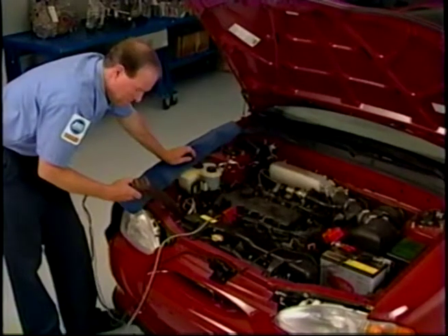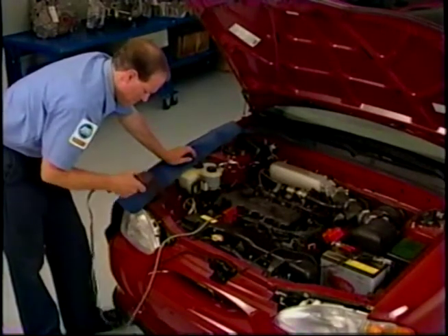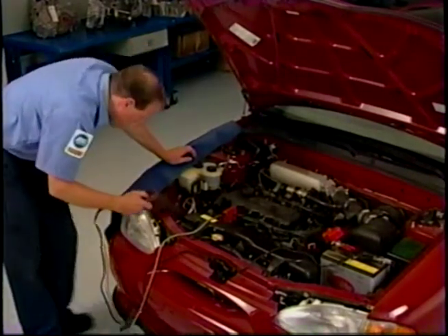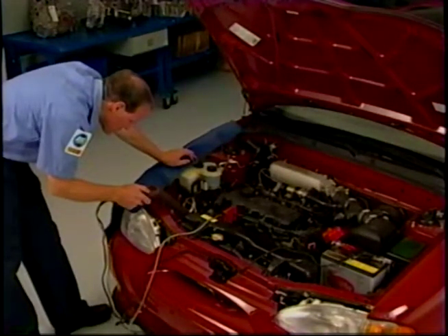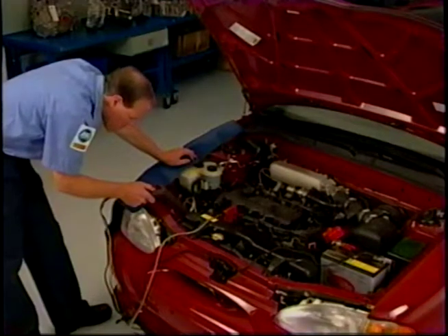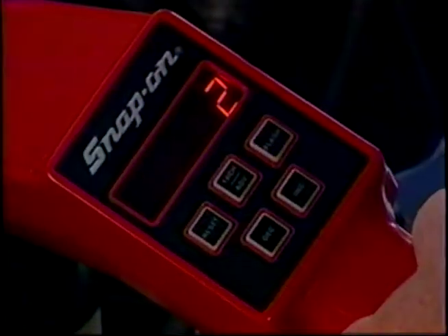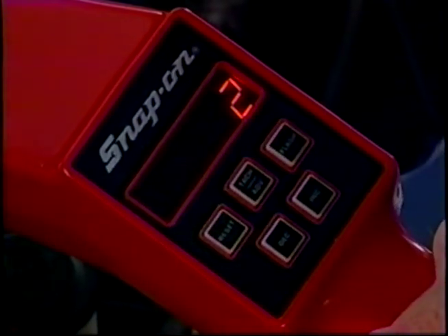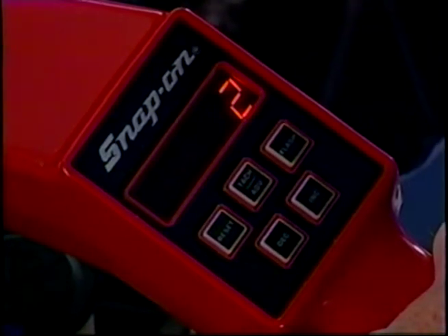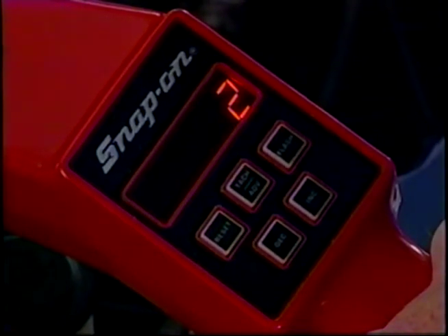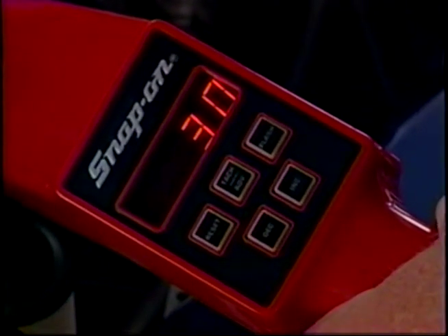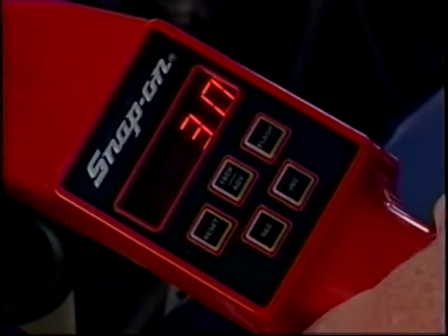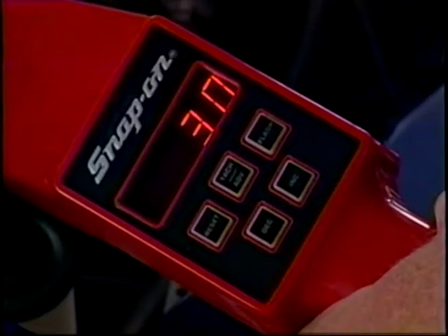Timing is adjustable on vehicles equipped with conventional or high-energy distributor ignition systems. Most distributorless or DI ignition systems do not have a timing adjustment. Retarded timing can cause problems with hesitation, backfires, poor idle, hard starting, and engine overheating. Overly advanced timing can cause a lack of power, hard starting, high-speed misfires, starter drag, and detonation.